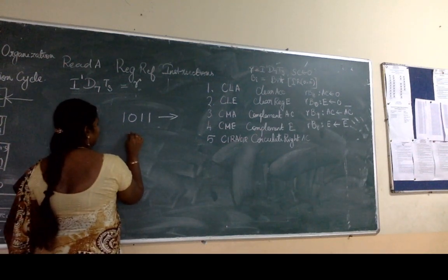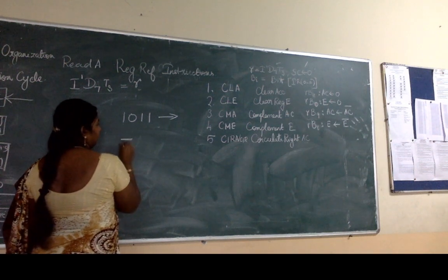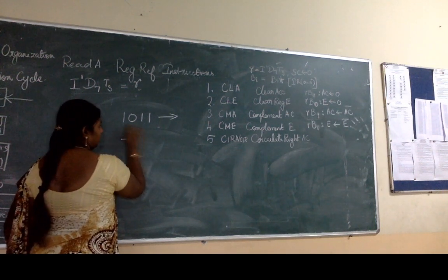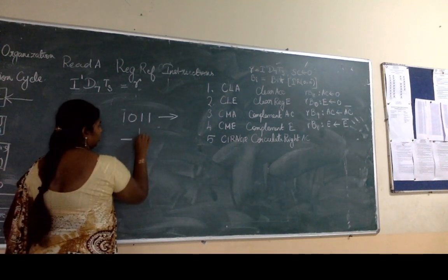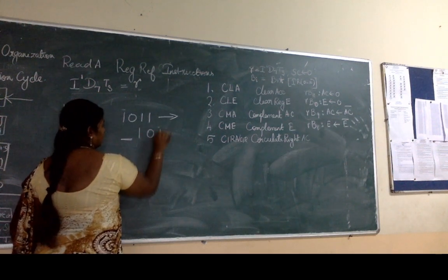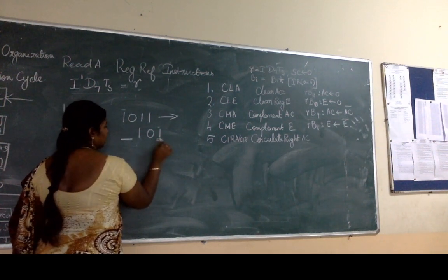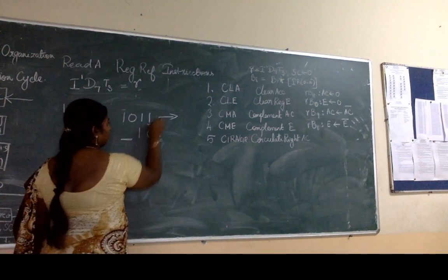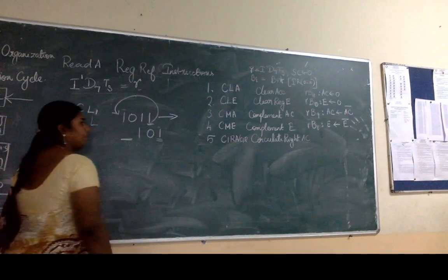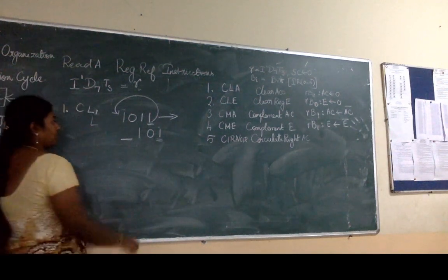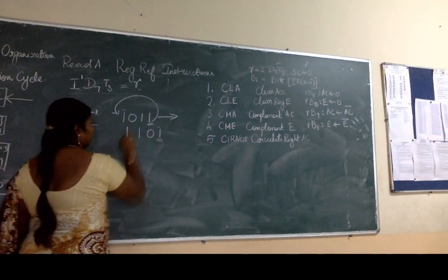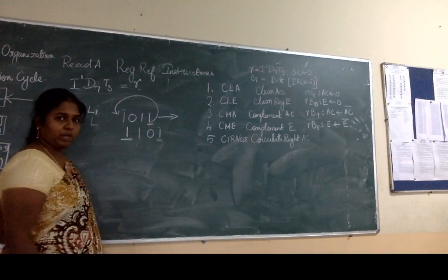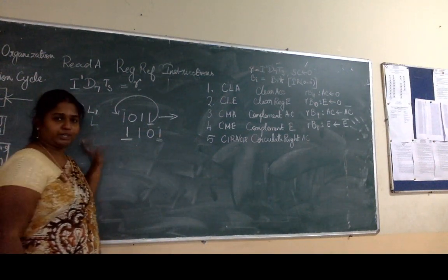So when I move that, I'm moving the bit MSB to the next position, 101. This one becomes my LSB, and the LSB of my input has to be moved back into the first position, or this MSB. So it should become 1101. This is called a circulate operation.